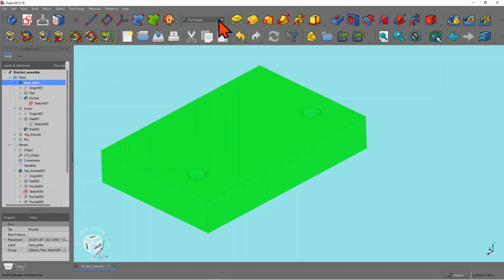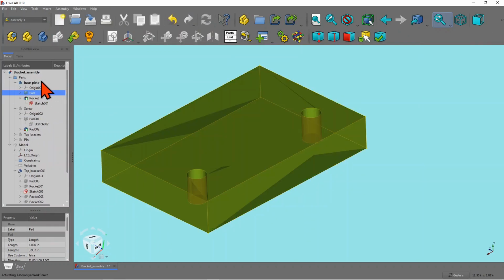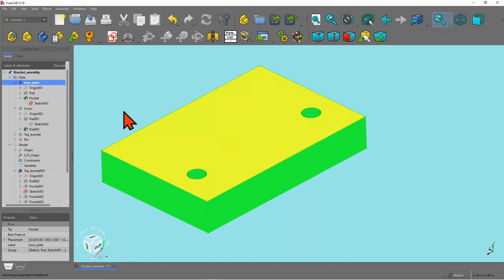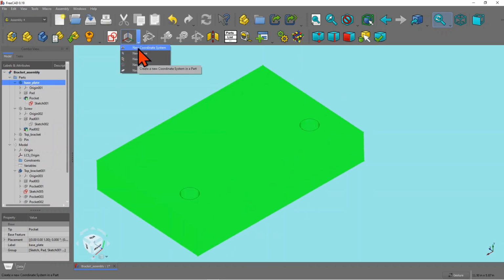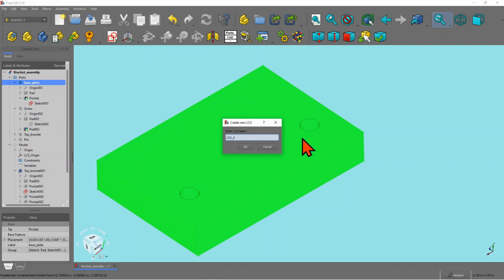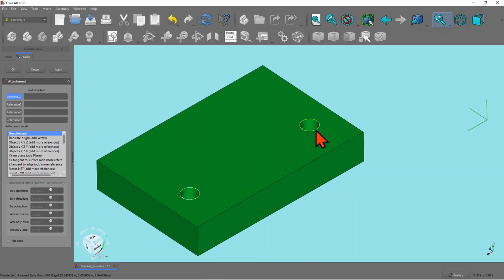Somehow I'm getting kicked out of that, but fine. Now I click on the base plate. Now it is active. Go here. So say base B, base plate LCS, and I'm going to select this circle and say inertial coordinate system.